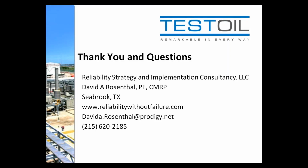And my answer is you need to filter those through your triggers. I like to know of all the failures you're hunting, how many of them took the facility down for more than a day? How many cost more than $50,000 to repair? The problem is in many sites that, yes, you're right, you will have more than 12, but the staff cannot handle more than that if they're done correctly. And the way to minimize that is to have effective triggers that you filter through to say which ones really deserve the full-blown root cause analysis work.